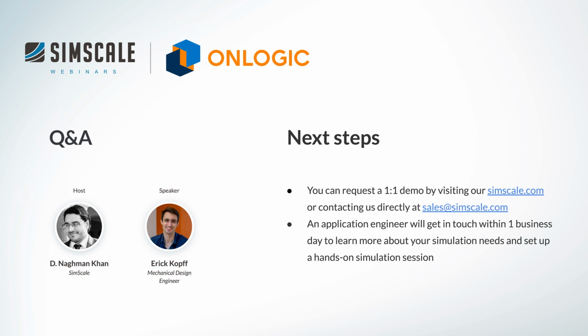So first of all, great question. The answer actually comes back to what I was discussing with the considerations that we as a team are constantly dealing with beyond the thermals of the system. For the most part, a flat plane wall, which is what a single fin on a heat sink is, is a fairly efficient way of removing heat from a piece of material, in this case, an aluminum heatsink.